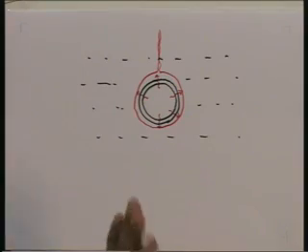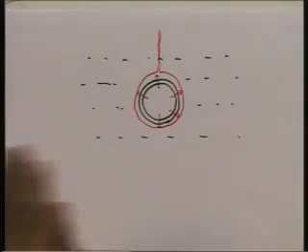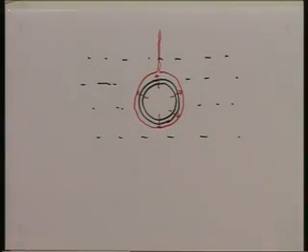Now, notice the similarity between this and what we saw in film condensation. There we had a film of liquid flowing downwards. Now, we have a film of vapor flowing upwards. One has to flow downwards because the liquid is heavier; here this has to flow upwards because the vapor is lighter. Keeping this similarity in mind, Bromley derived an expression for the heat transfer coefficient, basically doing a derivation very similar to the Nusselt derivation we talked about when we studied condensation.